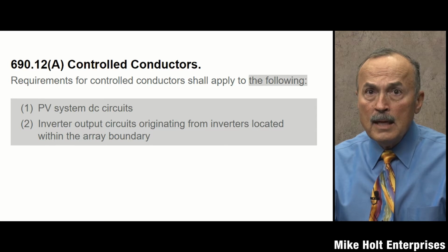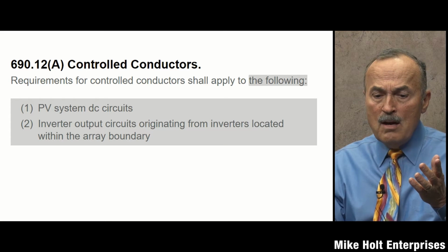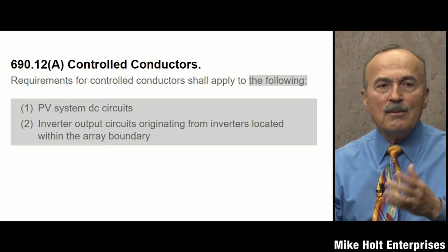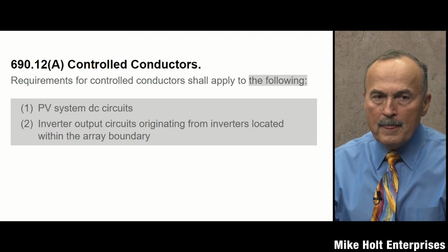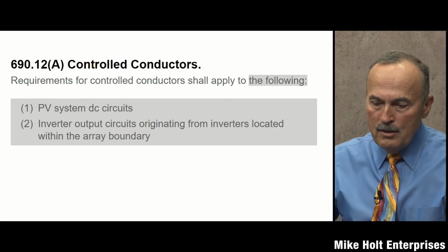Would that make sense to me? Like, okay, let's not put it in the array? Would that be a strategy? No, not at all, because the inverters themselves can be part of a rapid shutdown system. That's right. They're interactive, so that's part of the deal. The PV system disconnecting means could de-energize those conductors for you. Right, okay, got that.